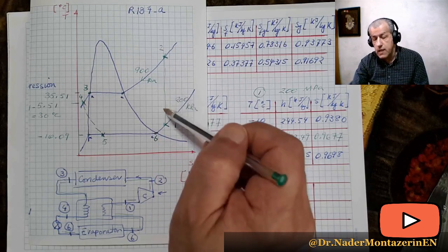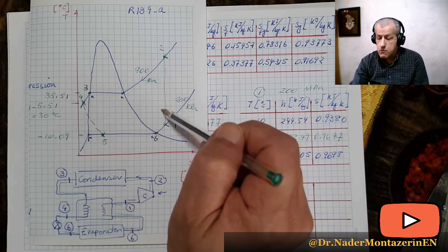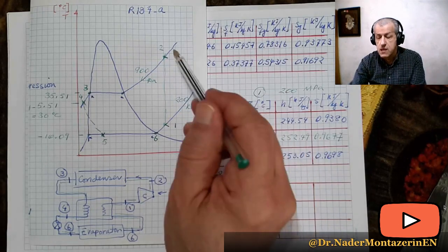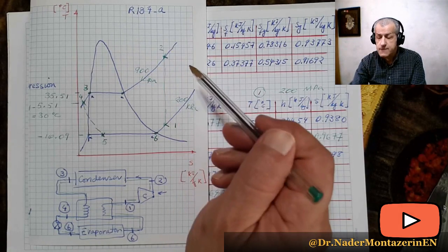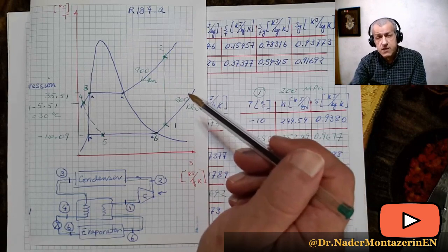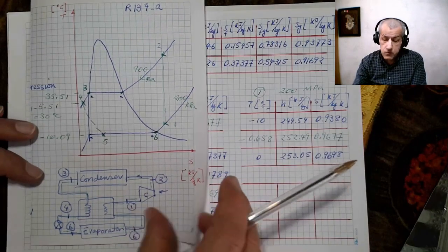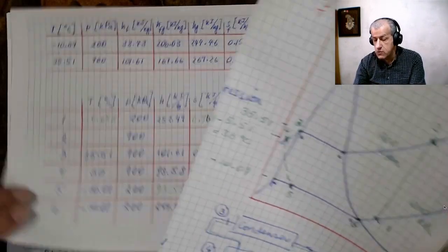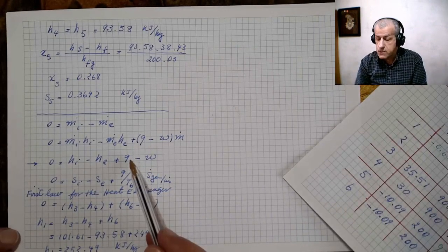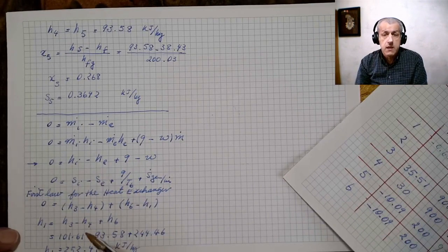Or it should tell us the isentropic efficiency of the compressor. So we would calculate the isentropic process and then use the efficiency to calculate the real process. Or it should give us some idea about the heat transfer, and therefore, once we know the heat transfer, we would insert that value into this equation and calculate the work from inlet and outlet conditions.